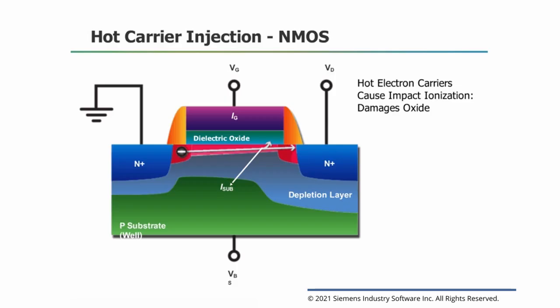Depending on the operation condition, one or more hot carrier injection mechanisms can take place in a single transistor. The injected hot holes and electrons can cause oxide and interface damage, eventually leading to device failure. For NMOS devices, the threshold voltage typically increases due to the predominant electron trapping, and this increase, coupled with a mobility decrease, results in a smaller drain current.